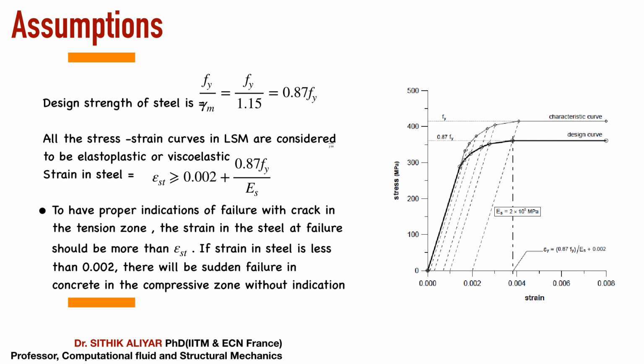In steel, there is a similar stress strain graph. I hope you have studied the mild steel stress strain graph. It is the stress strain graph given in IS 456. As I explained earlier, how from FCK you reached 0.67 and then 0.45, similarly here you reach Fy. Beyond this, if you apply load, strain hardening, the plastic zone, and rupture will all happen, so we have a graph only up to Fy.